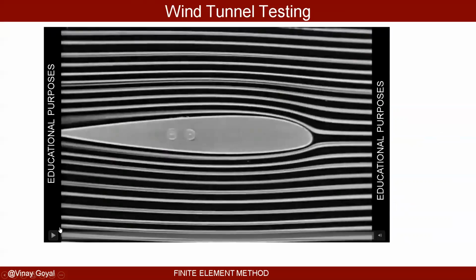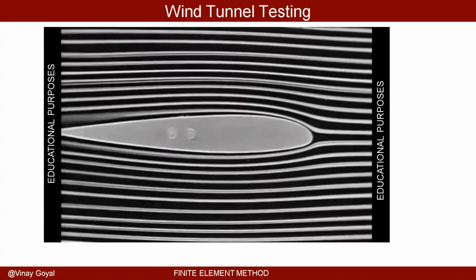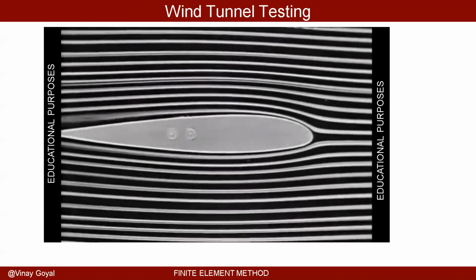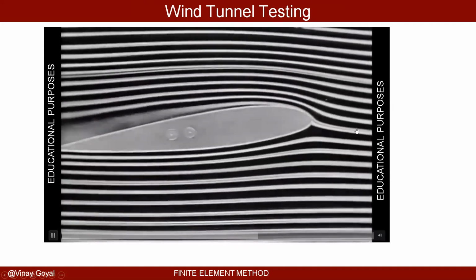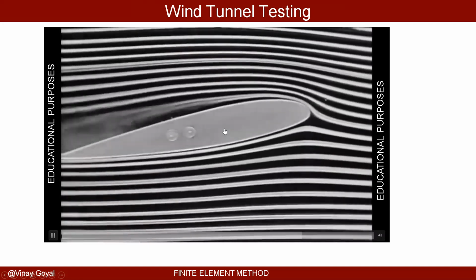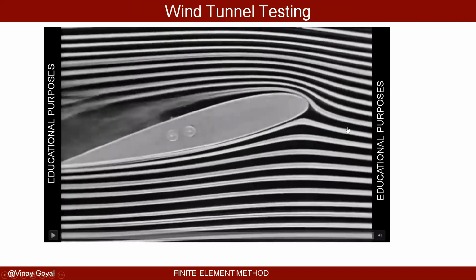And here I'm going to show a quick video of an airfoil in a wind tunnel test. And that's what's going to help us really characterize the behavior of lift. And what you see here is a wind tunnel test. Usually, powder or some fluid is passed through. And you can see here the angle of attack is being changed, and they're measuring forces and things like that. You can see here you start to have flow detachment in this area, and here you're going to have a stagnation point over here.